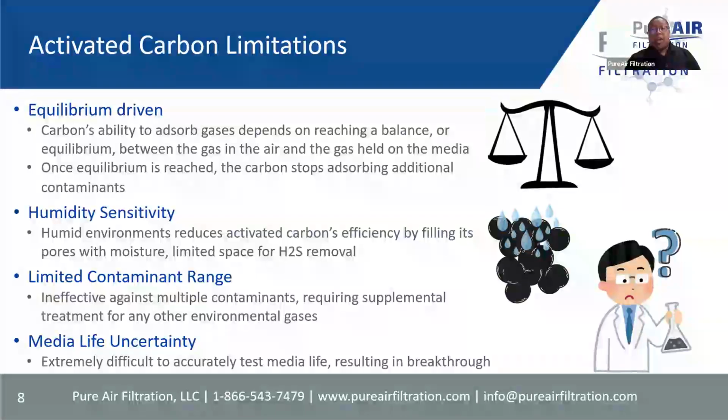Activated carbon also has a humidity sensitivity, so it treats water vapor as a competing molecule. In high humidity conditions, particularly wastewater treatment plants where H₂S is common, water molecules will occupy more pore spaces, leaving less room for H₂S and other targeted gases. This will lead to quicker saturation of the activated carbon and a significant drop in performance.